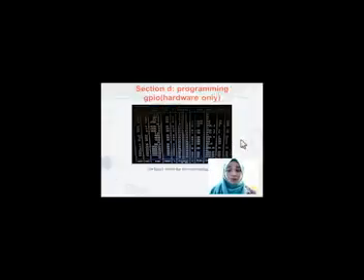Before we build the circuit, we must understand and know which pin we need to use. So, by using the command gpio readall, we are able to know the pin number, GPIO number, the name of the pin, and the mode of the pin. So, it's very crucial to ensure the circuit is put together correctly, so that our circuit will work functionally. Thank you.